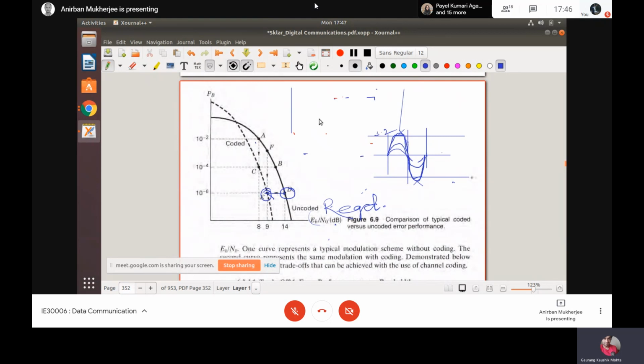So suddenly each square wave will be switched, and each square wave switch means your fundamental frequency increases. Fundamental frequency increase means, say, 9f0 minus f0, so 8f0 is your bandwidth. So that will also increase. So that is the bandwidth requirement.